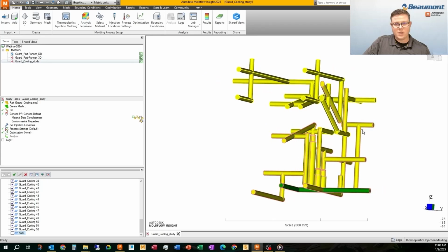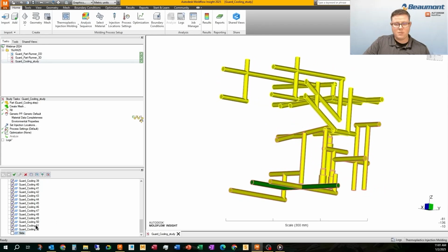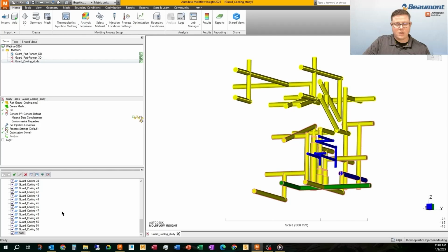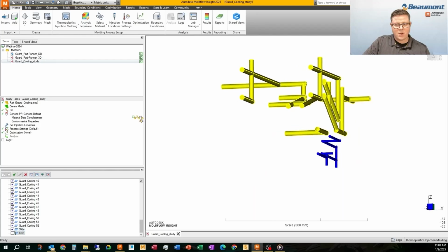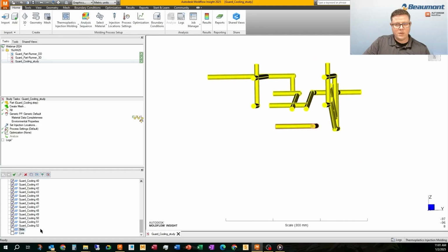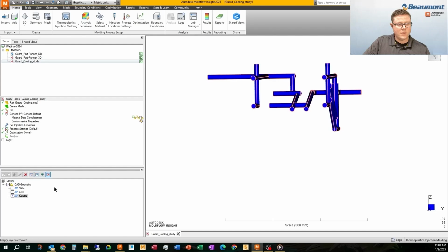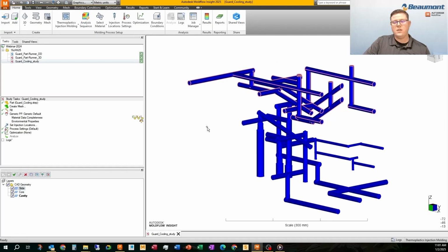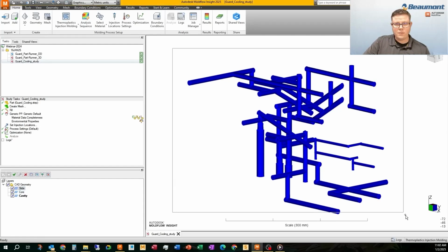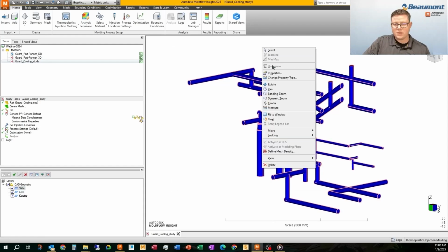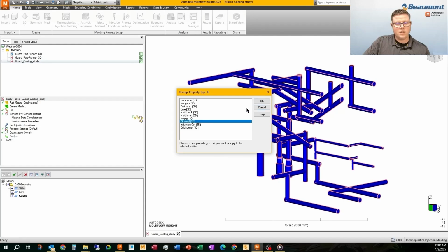So what I'm doing here is I'm just going through and I'm going to select my core, cavity, and slide and name them accordingly. So I'm selecting my bodies. Now you can see I accidentally grabbed a part of that core line. I'm just going to keep going through, creating new layers. So now I have a slide, I have the core, just assigning them. And then last but not least, the cavity. Now I've got only 3 layers I'm looking at instead of multiple layers per body. Highlight everything, assign the properties to a channel 3D.